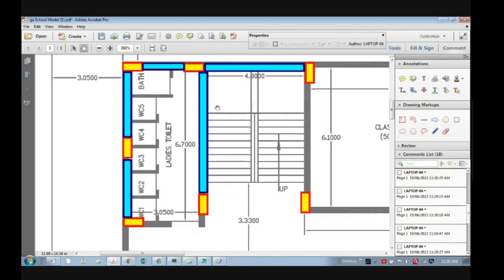Can you see the offset here? Yes sir. Here my face is being drawn on this side, and after coming here it is resting partly on the beam and partly on the column. And generally this is not a good choice from a structural point of view. If it is unavoidable, you can take that decision. I don't have any issue, but it is not a good choice. So can you avoid this offset of the beam?